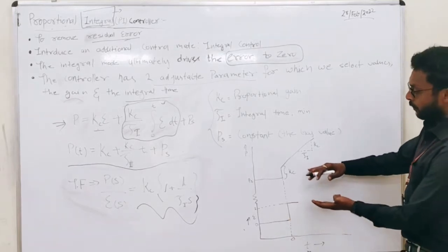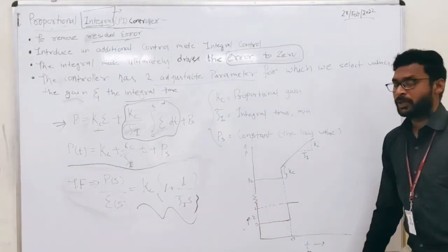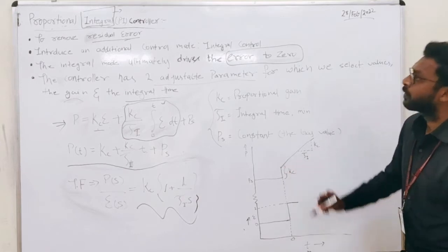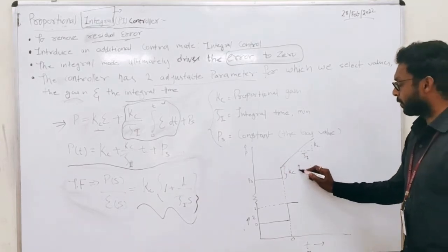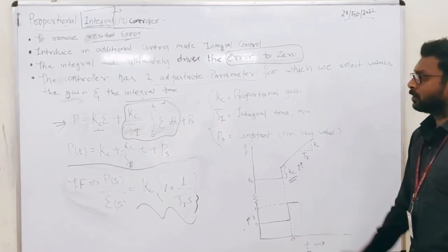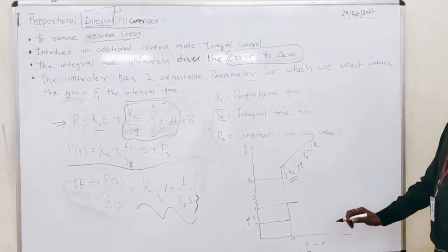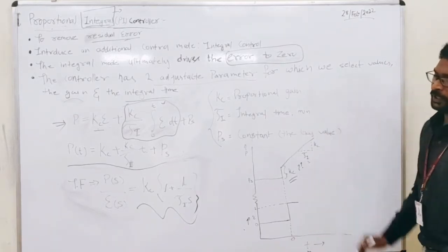After that, we are breaking down the graph between the 1 and Ps value. And here, from the Ps, we have an error, so that error we will find out. This is the constant Kc value, that is the proportional gain, and we will find out the Ti value from the slope.